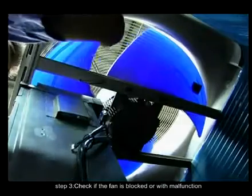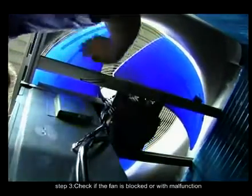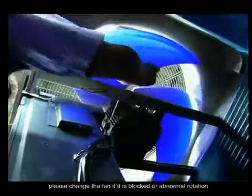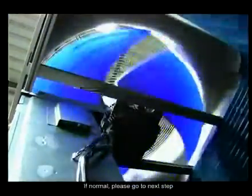Step 3. Check if the fan is blocked or has a malfunction. Please change the fan if it is blocked or has abnormal rotation. If normal, please go to the next step.